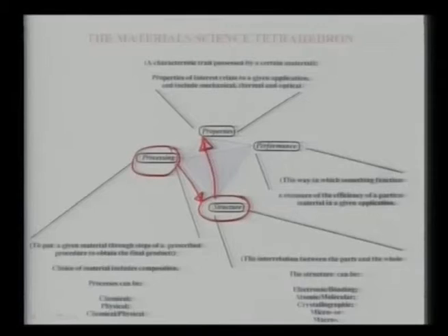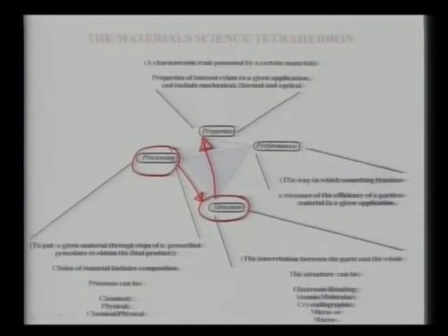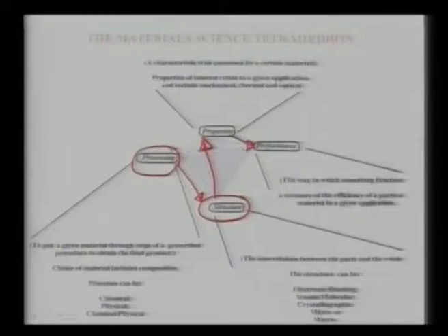Now, if the structure is changed, then this structure will definitely influence properties like hardness, fracture toughness, and strength. If the material is completely dense, it will have better strength properties. If the material is porous, it will have poor elastic modulus and poor strength. If the material has inferior properties, it will lead to very poor performance, whether structural performance or biological performance and so on. So what I am trying to say here is that processing, structure, property, and performance are all correlated with each other.